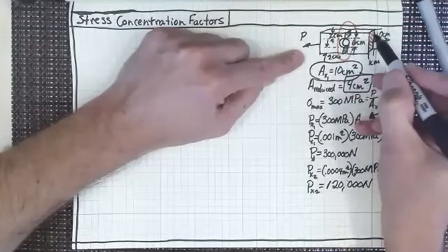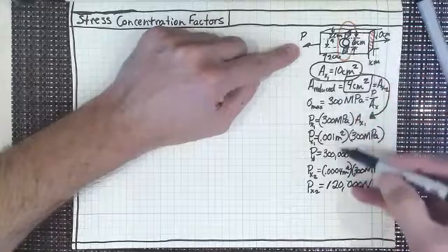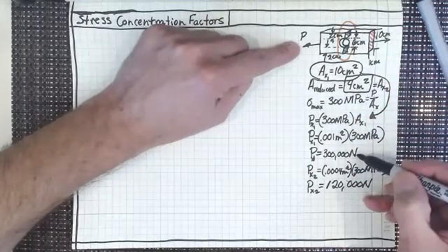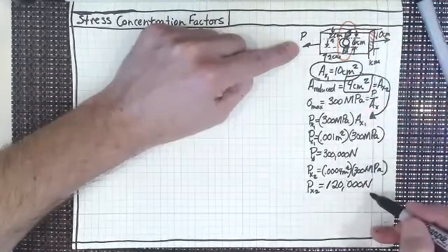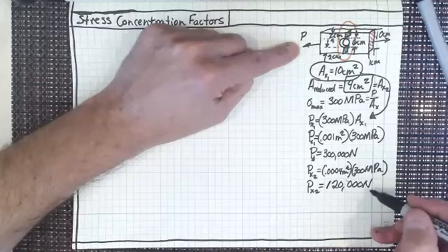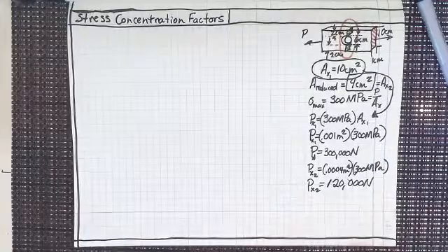So yeah, I can't use the cross-sectional area of this. So I can't put the maximum 300,000 newtons on there. Because of the cross-sectional area here, I'll have to reduce it down to 120,000 newtons. Right? That's what you're saying.